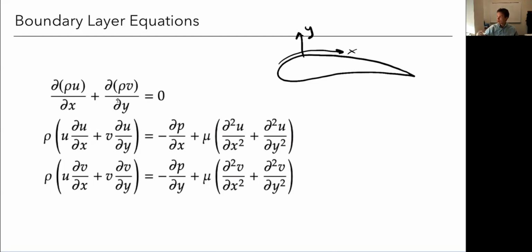So locally, if I'm calculating the trajectory of a football or something, I wouldn't account for the fact that the ground is curved, even though as I keep going further and further, there's some curvature. And that's just because the height I'm looking at is very small compared to the curvature. The same kind of approximation is applied here in the boundary layer, that these are very thin relative to the curvature. If the curvature is significant, for aerodynamic shapes, typically that would only be during the leading edge. So it's a very small portion, and there is a curvature term we can add.